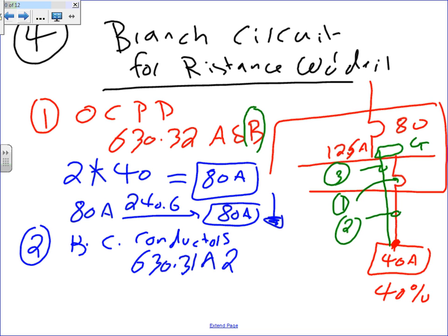Now let's look at the conductor, though. The conductor is an issue. For conductors, look, Chris, what we're going to do for the conductor: take the 40, multiply by the multiplier from the welder side for 40 cycle. My cycle is 40 here. What's the multiplier for 40 cycle from the resistance welding? 0.63. Thank you. That will give me what? If you do the math on that, what do you get? 25 amps. Thank you, sir. 25 amps. Okay, no problem.